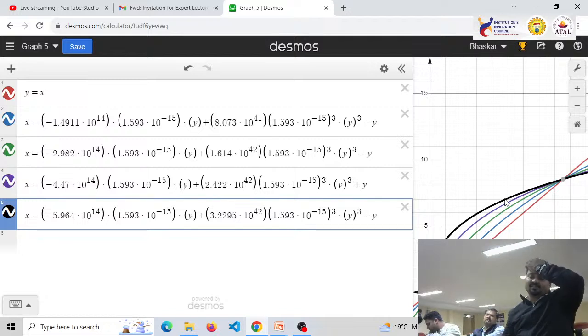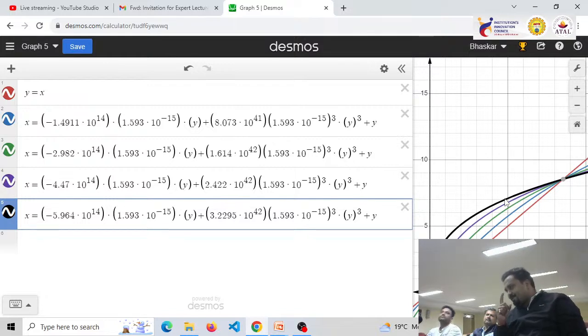Similarly, the second way to confirm the presence of negative capacitance is the voltage drop across one of the components. As Kirchhoff's voltage law says, the voltage drop cannot be greater than the supply. But here, I have got a voltage drop across one of the components that is higher than the supply voltage.